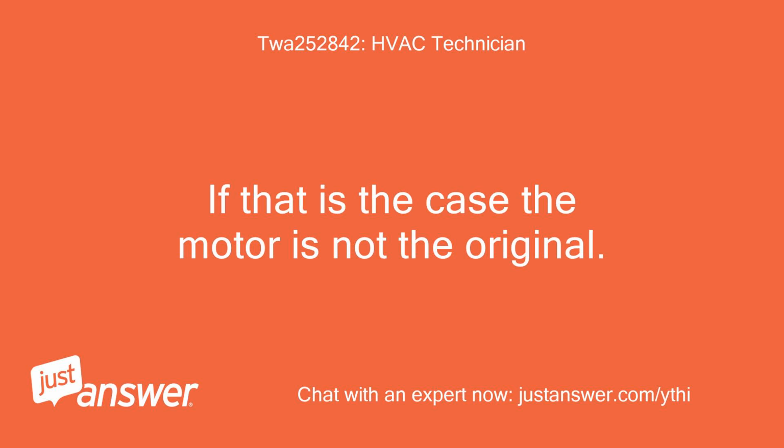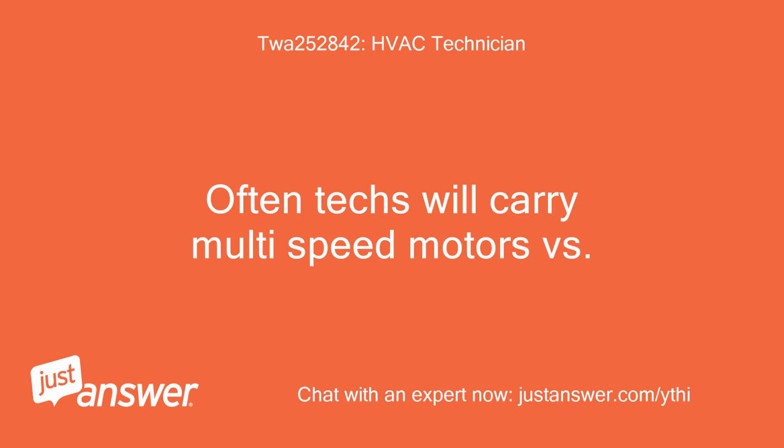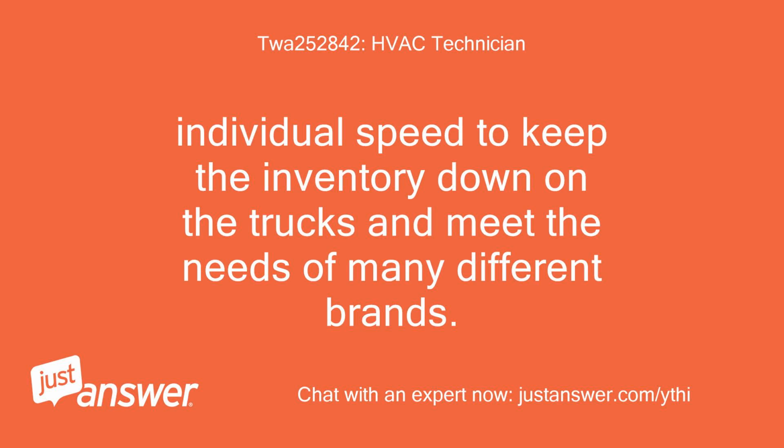If that is the case, the motor is not the original. I say that because most OEM, original equipment manufacturer, condenser fan motors are not multi-speed. Often techs will carry multi-speed motors versus individual speed to keep the inventory down on the trucks and meet the needs of many different brands.